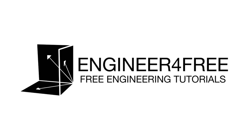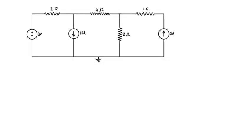Hey, welcome back. I've got another example here on using Supermesh analysis to find all of the branch currents in this circuit. So we've got three power sources, we've got three different loops, but the important thing here is we have a current source in between two loops. And when you see this, and if you were asked to use mesh analysis, this immediately means you have to use Supermesh.